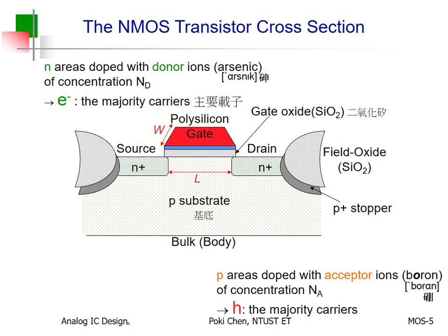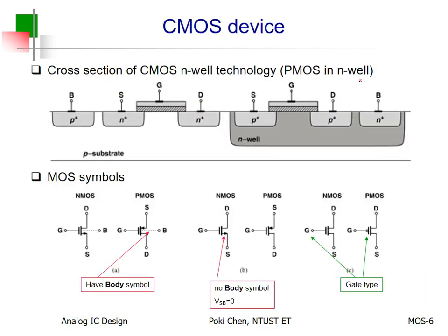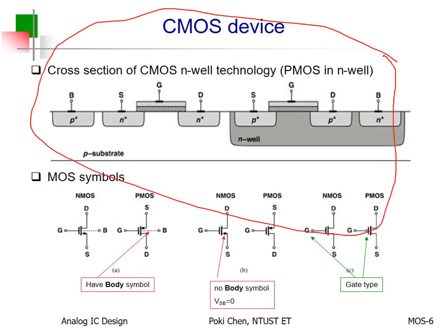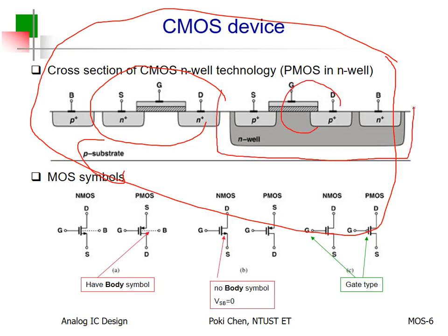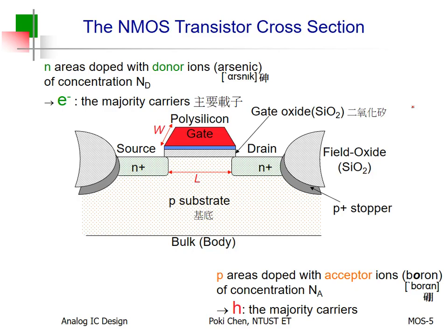So this is the real structure for a mature CMOS process. You can see the P substrate here, so you can directly fabricate NMOS. But how about PMOS? You need help from another layer. We call it the NWell. That's it. Easy to test, right? But very hard to fabricate from the beginning for humankind. It took 30 years for humankind to make it. Wow. All right?